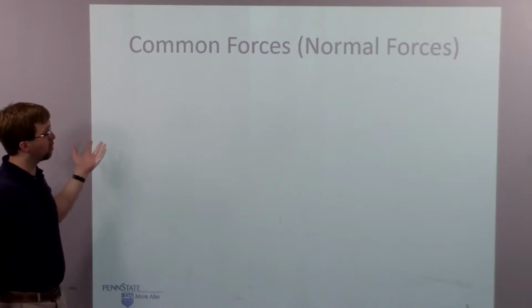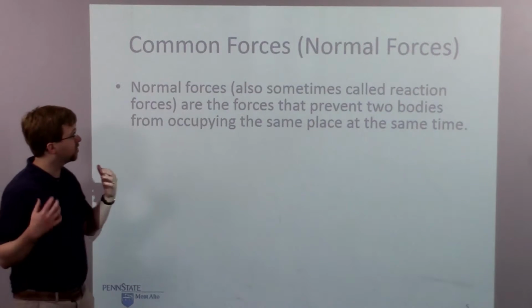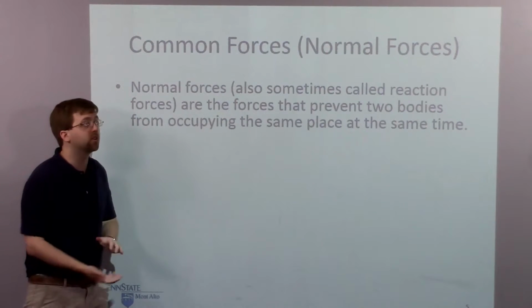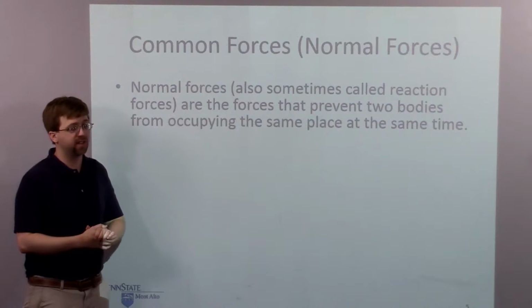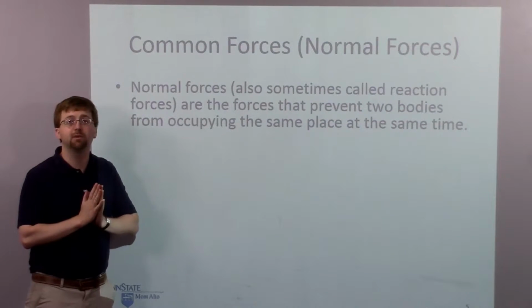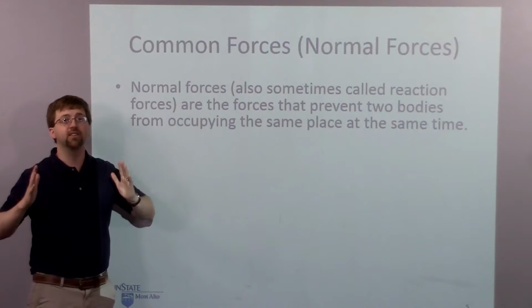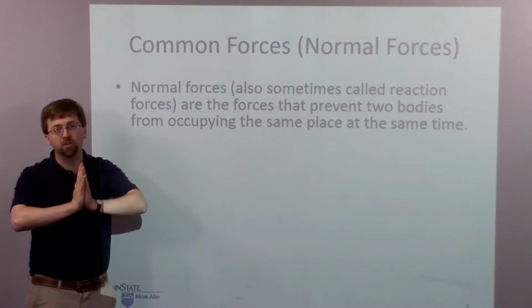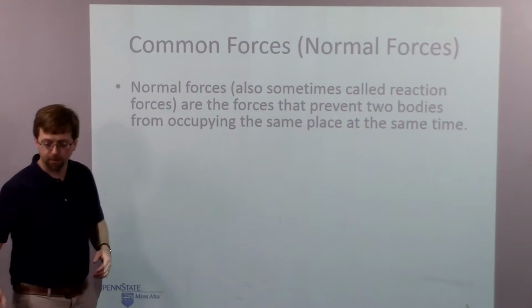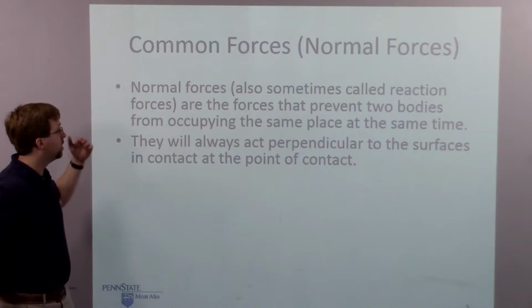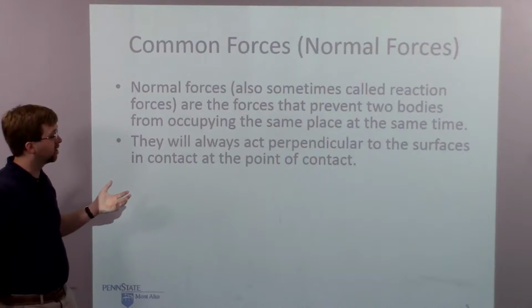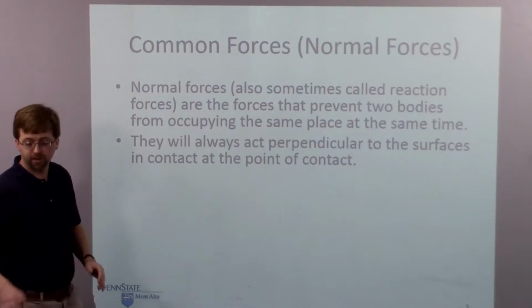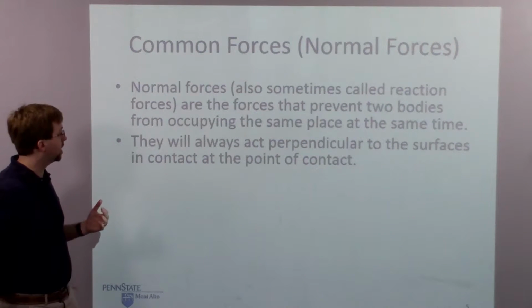Alright, next we've got normal forces. And a normal force, also sometimes called a reaction force, is the force that prevents two bodies from occupying the same spot, same place at the same time. So anything in contact is going to have normal forces keeping those bodies separate. They will always act perpendicular, or normal, to the surfaces in contact. That's where the normal force name comes from.